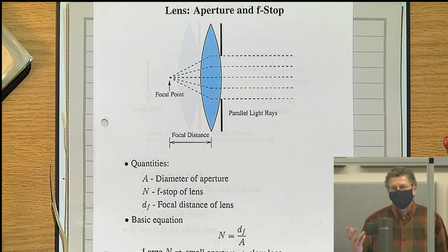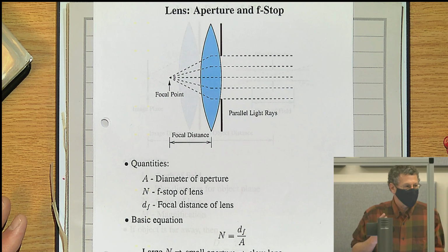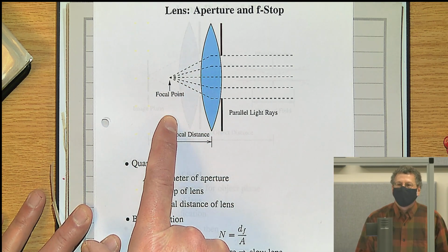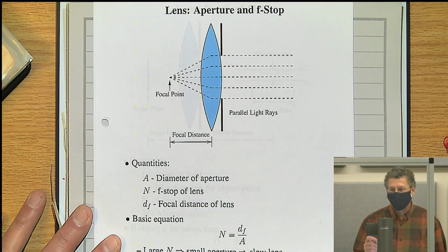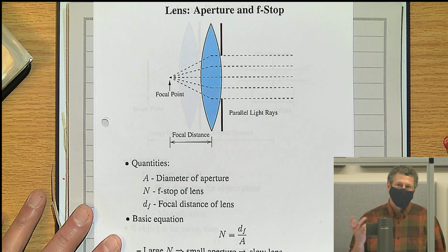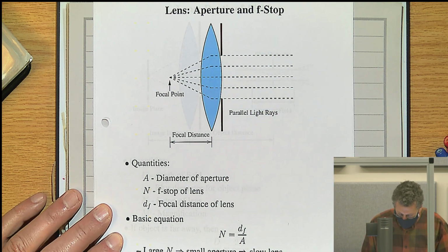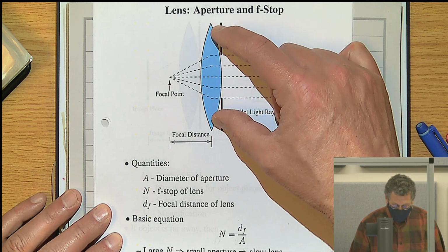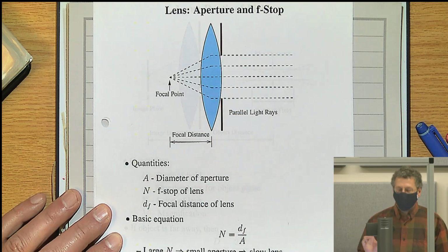And that's sort of what happens with a pinhole camera. So anyway, you can think of them as being Fourier transform pairs, okay? But the difference is that the image you sense at the sensor, you're sensing the energy. So you're actually sensing the square of the signal. You're squaring the signal because you're measuring the energy, because the energy is the voltage squared. Okay, so they're a Fourier transform pair, and so you have the aperture, and if you make the aperture big, you let a lot of light in. If you make the aperture small, you let just a little bit of light in.